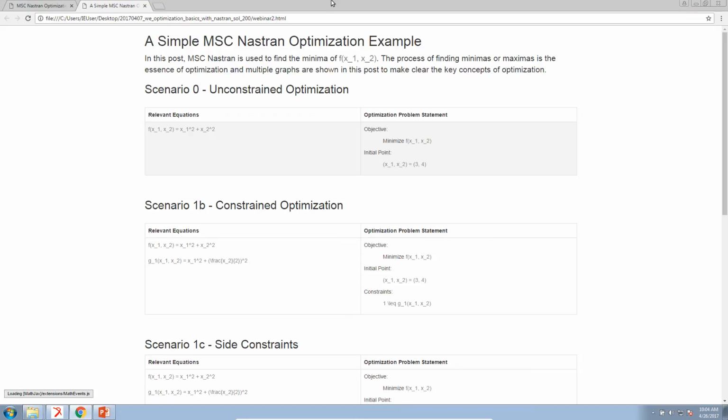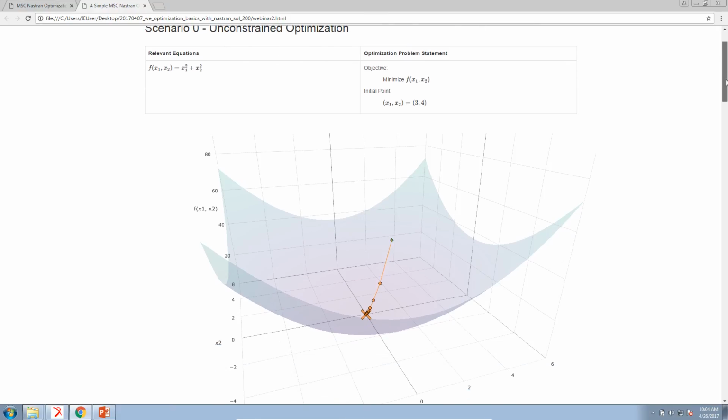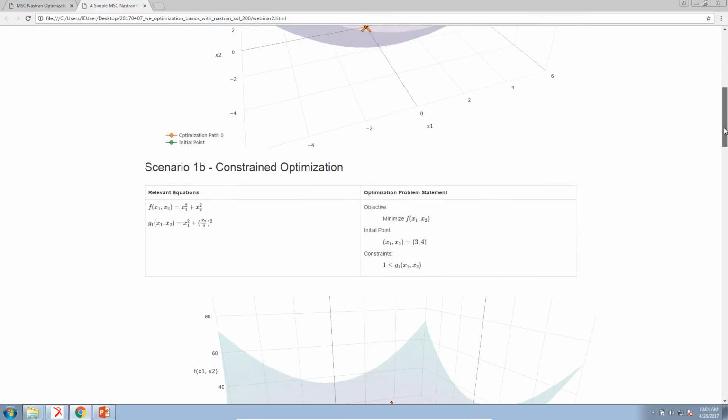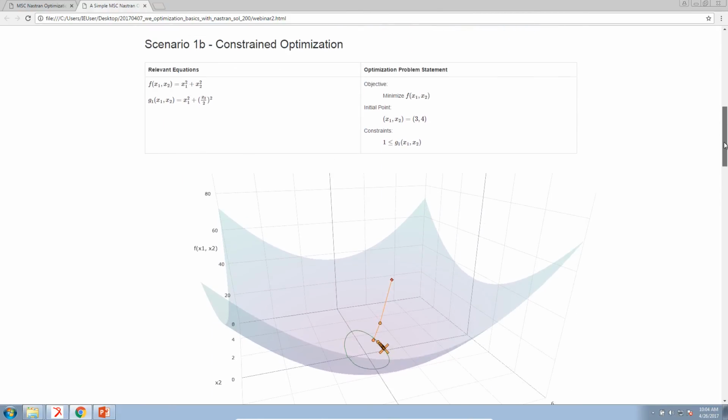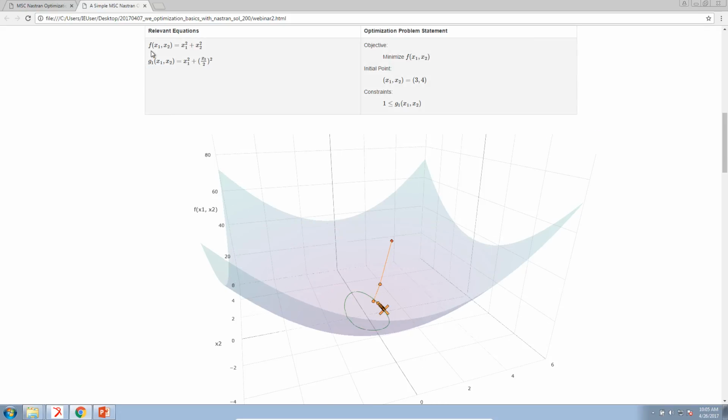As an example, if you're dealing with structures, if you want to minimize the weight of your structure as much as possible, your function could be weight, and the variables could be structural dimensions of the structure. Then your objective would be to minimize or find the minima of your weight function with respect to those design variables. Here on the screen, I have a very simple 3-dimensional function. This plot that you see here is this function f.